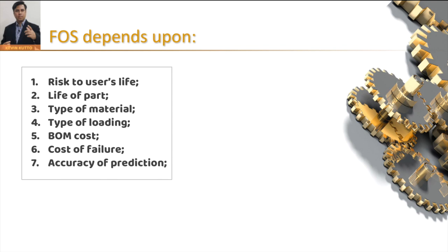And the last but not least, accuracy of your prediction. If you are designing something totally new, for the first time, and you don't have enough data, you don't have enough understanding, definitely there is a chance that your assumptions will go wrong when you are calculating working stress, right? So you have to take a higher factor of safety, obviously.